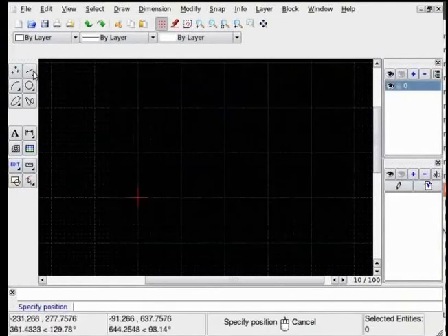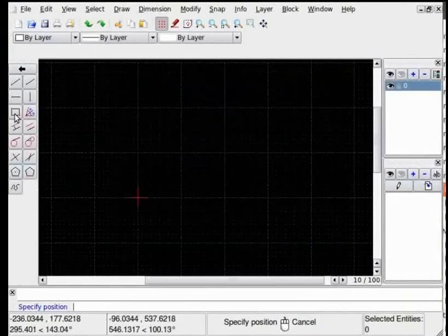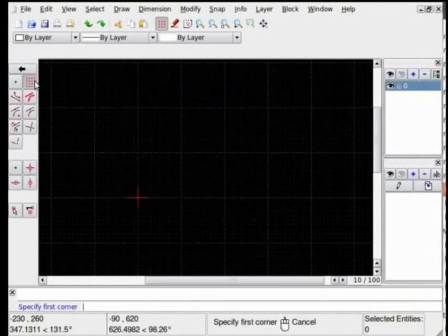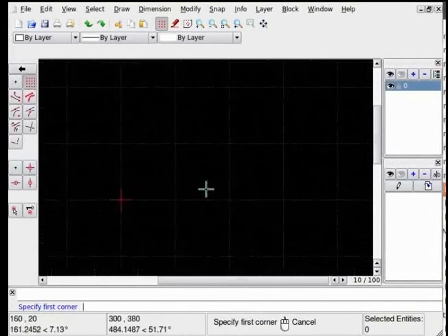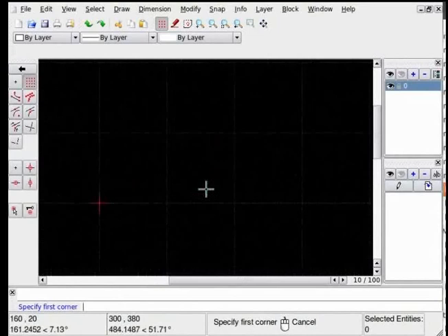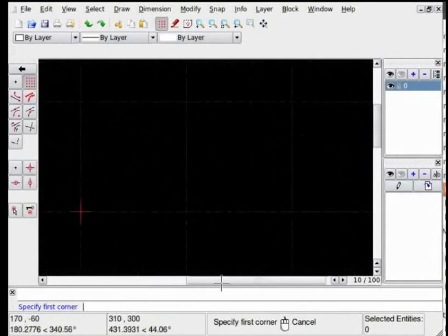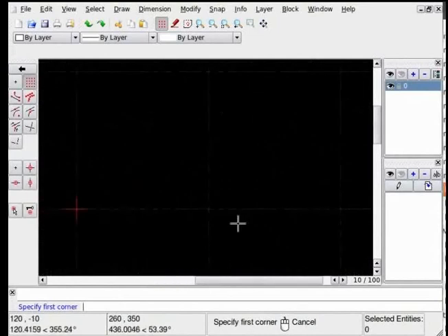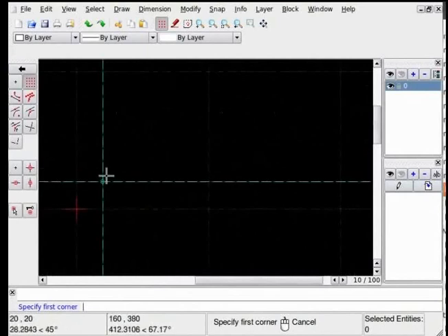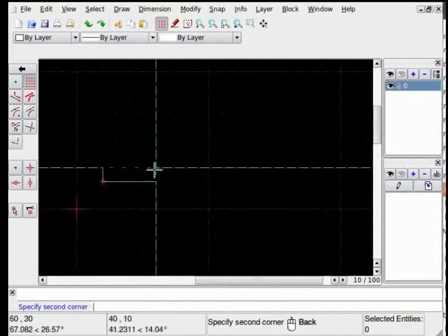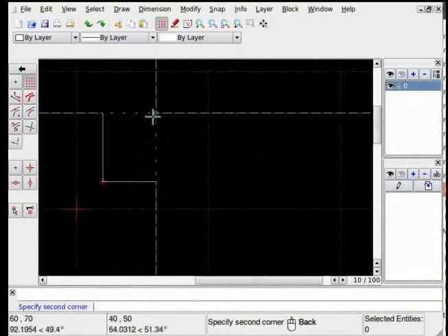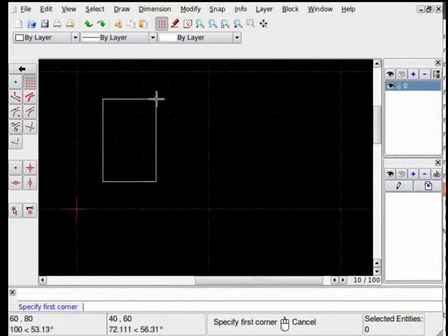From toolbar, select Line tool and click on the rectangle icon. Choose Snap to Grid option. Zoom in on your drawing area by using middle mouse button if your grid size is too small. I'll create rectangle of 4 grid sizes by 6. So left click for the first corner, and again left click to complete it.